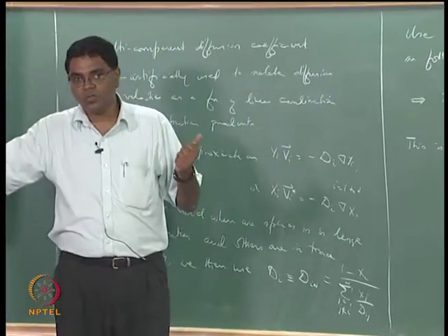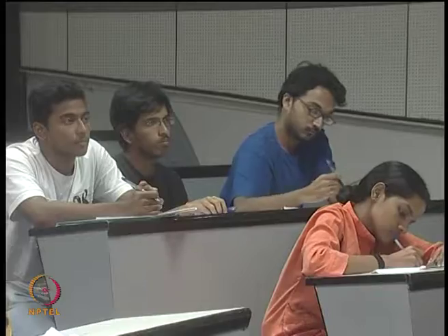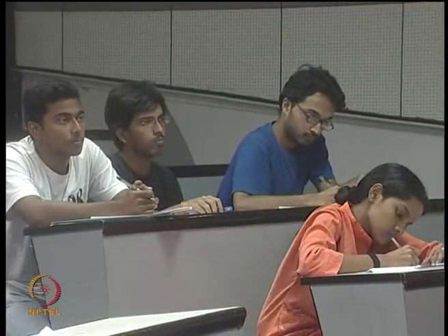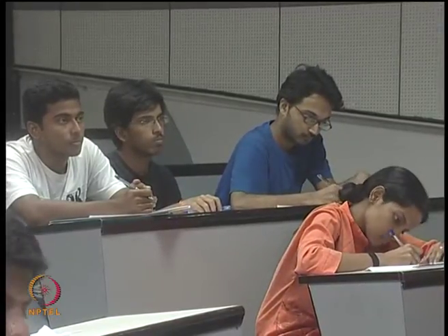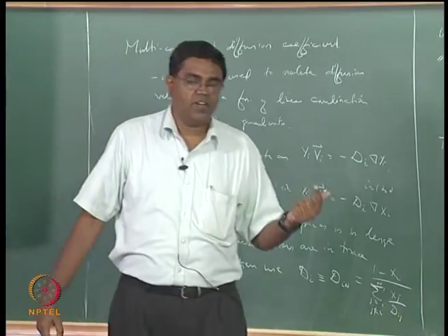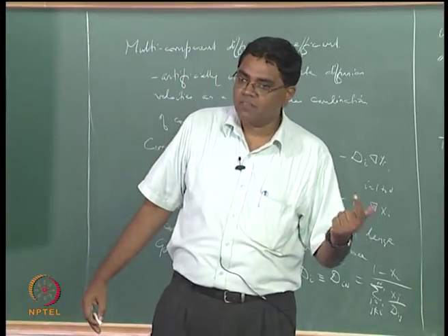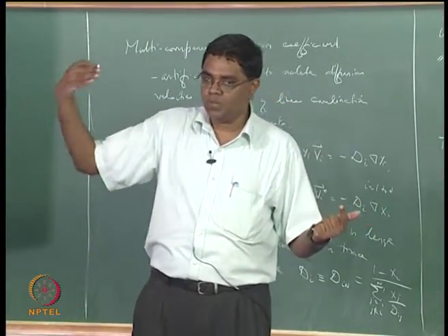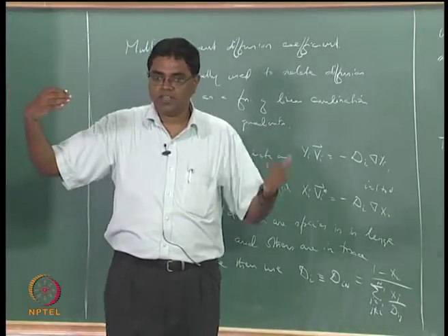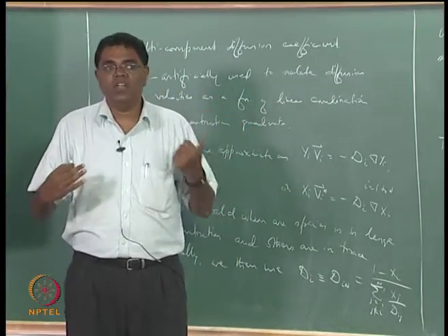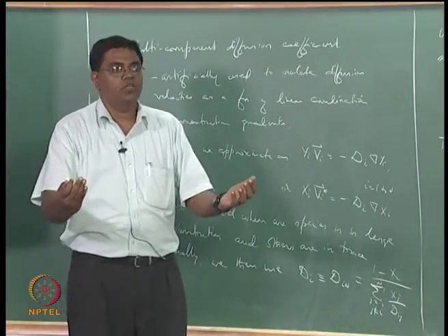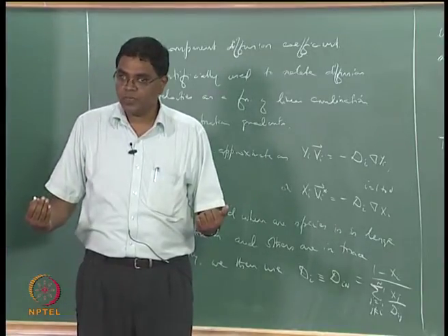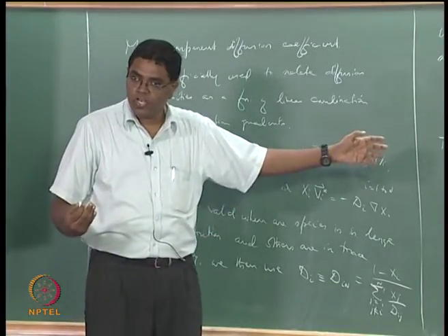The corresponding equation is the overall continuity equation. Then you have the mass-averaged mixture velocity that shows up in the overall continuity equation. That is an unknown for which we typically resort to the momentum equation for the mixture, which is what we would now go ahead and do.